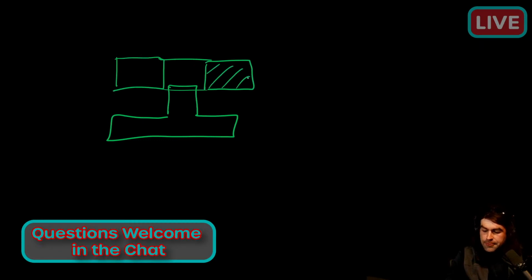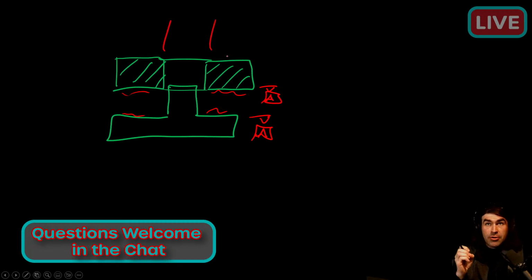I think the key is if you need the flat parts to be flush, like it's sealing or something, those need to be the primary datum. That's going to be your best way to do it, and then you're going to control the diameter to that, so when you set your virtual conditions, they're not going to get kind of squirrely on you. That's exactly how I would do that.